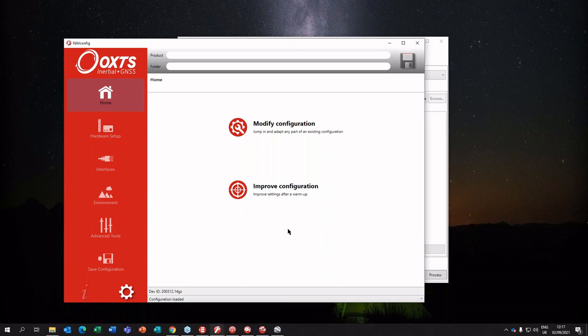And when you want to get centimeter level accuracy in your survey, obviously you need to get that more precise. But the INS is going to be doing that automatically. So typically you would only need to measure, say, to the nearest 10 centimeters, and then the INS will do that. As you do the warm-up, it's figuring out exactly what the configuration is.